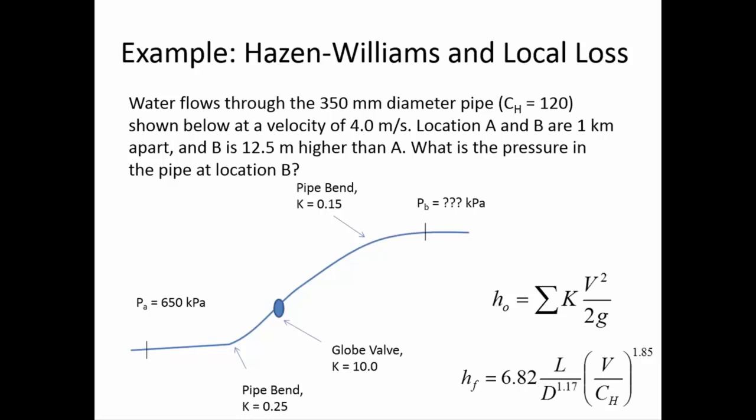That's a good question. That globe valve lost us most of the local losses. So that would get us probably another 8 meters of head, which works out to roughly 8 times 10. You know, we get 80 kilopascals out of that. So that would get us to 100. We'd be most of the way there, but not quite all the way if we wanted to be at no less than 140.